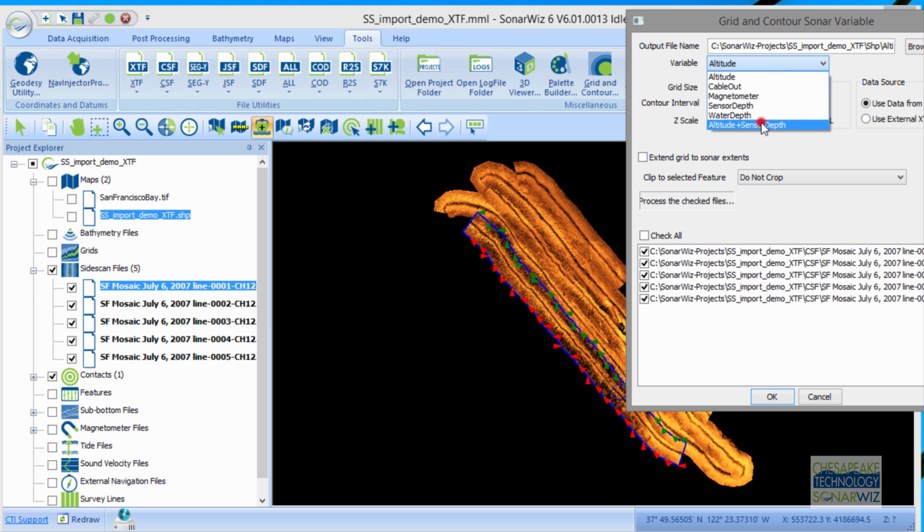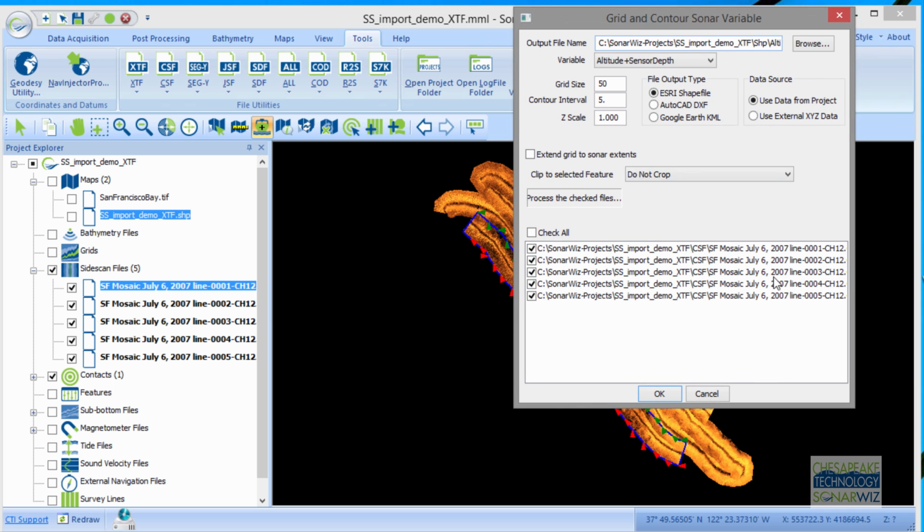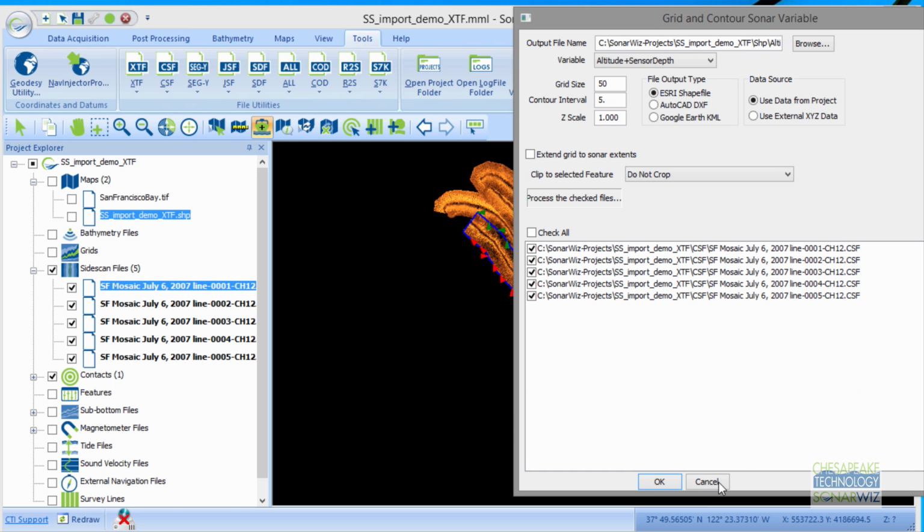And it gives you a really nice view of your data. It gives you a sense of the depth. It's about as good as you can do with side scan in terms of getting depth. If you want to see a little bit more detail, like if you had the EdgeTech 4200, this may be as good as you can do. If you have an EdgeTech 6205, this is an interferometer. It's going to collect bathymetry data, very accurate data. And with SonarWiz, you get backscatter, which looks a lot like side scan, but it's highly accurately placed, as well as getting the bathymetric data. So there are some good things to give you an option in the future, in addition to your side scan data processing, if you ever consider renting or buying an interferometer.